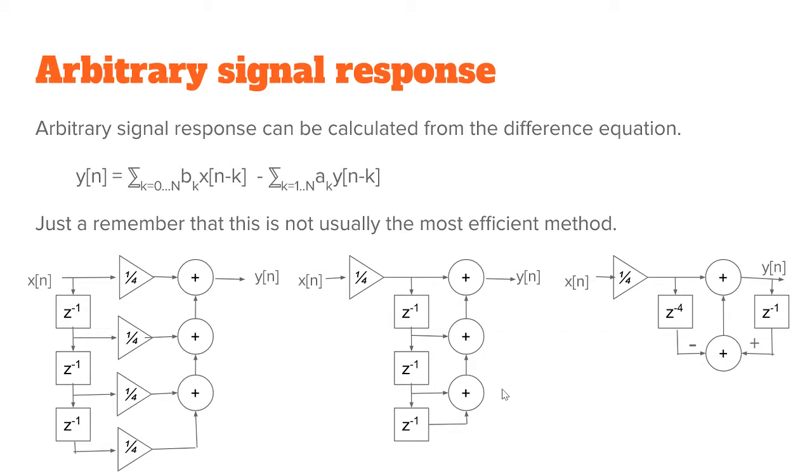The same way on this linear time invariant system, there are different methods to optimize the calculations. For example, if we have a symmetric impulse response for FIR, then we can actually calculate the multiplication before adding. So it halves the amount of multiplications.